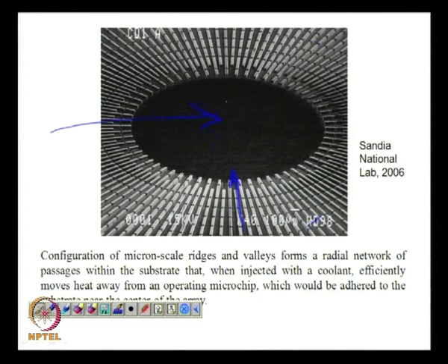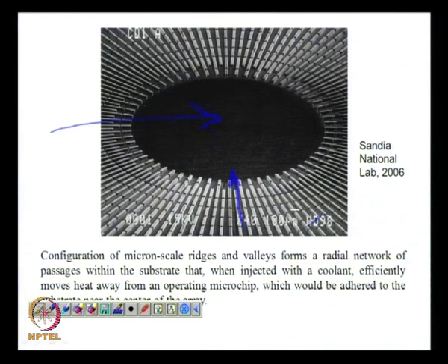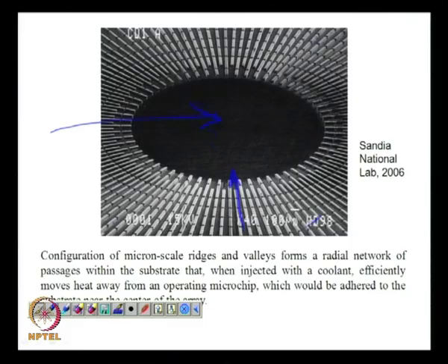And another silicon wafer would be bonded on top of this. So it's going to provide a cover that will not be grooved. So that's going to create the closure for these grooves, and through the grooves the liquid will flow, and some portion of the groove will be utilized for return of the vapor towards the cooler section. So this is how the entire process will keep on extracting heat from the center towards the periphery.